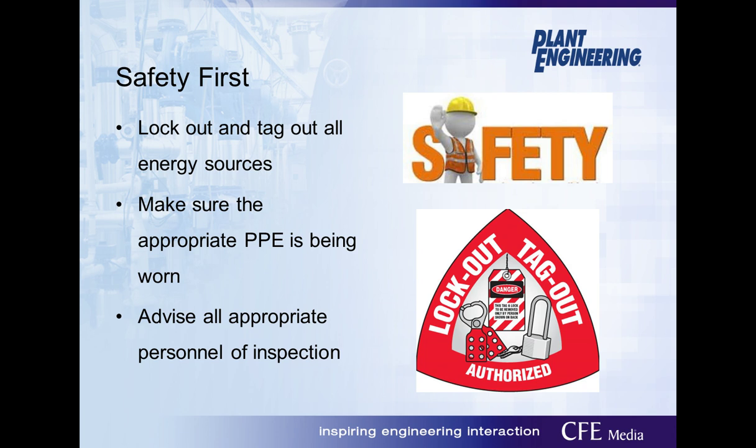I always like to include the importance of safety and how it should always be the first priority of troubleshooting, not only on AC induction motors, but on any piece of rotating apparatus equipment in a facility. When troubleshooting a motor that you are going to have to physically touch any part of the motor application or have to remove any safety guards to troubleshoot, please make sure that proper PPE and lockout-tagout procedures are followed. It is also a good idea to advise all appropriate personnel of the inspection. You do not want anyone to not be aware of what is going on and accidentally put your safety in jeopardy. Because at the end of the day, our main goal is to be able to all go home to our families without any injuries.